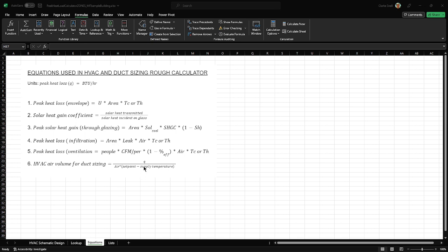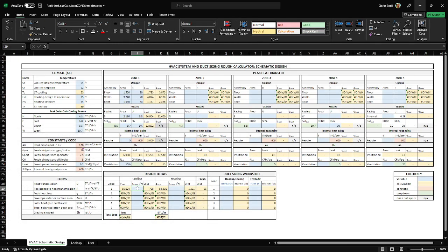So that's going to have a big effect on how much air we need to move. You just have to look at that and think about it, or we can talk about it in class. The point is, I need a cooling supply temperature. So I'm just going to say, and this is something we'll talk about later, typically for cooling, 55 is very common.